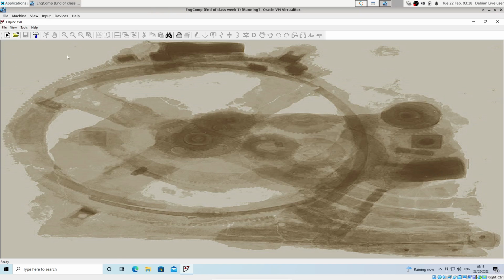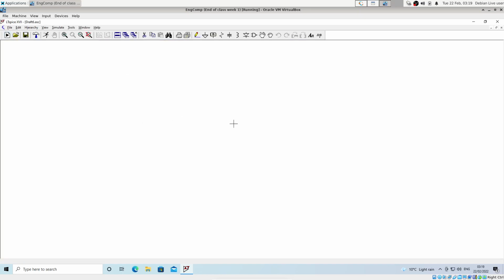It's a great simulator. It has some quirky interface elements that feel a bit dated, but actually it's a terrific tool once you get used to those things. So first thing I'm going to do is create a new schematic from this button on the toolbar here. What they mean by the schematic is basically our circuit diagram, where we're going to define which elements are in the circuit, and then we're going to define some other properties for the simulation, and it'll actually generate waveforms representing what the voltages and currents look like in the circuit.